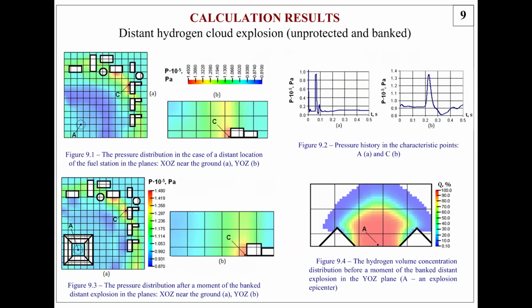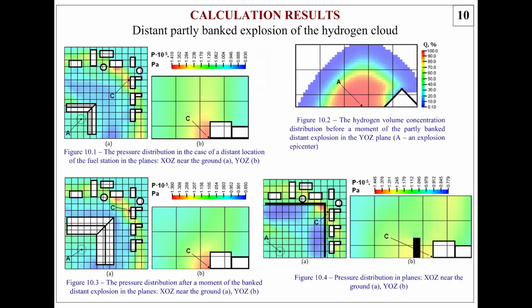Installing a protective device around a potential compressed hydrogen release site significantly changes the hydrogen concentration field before the explosion. The presence of an obstacle in the path of the blast wave also restructures the maximum pressure field, which reduces the impact load on buildings. Variants of different heights for partially surrounding the explosion site with a protective structure were also considered to assess the possible consequences of the accident on the surrounding buildings. The most effective protective device was a solid wall in the immediate vicinity of the buildings.